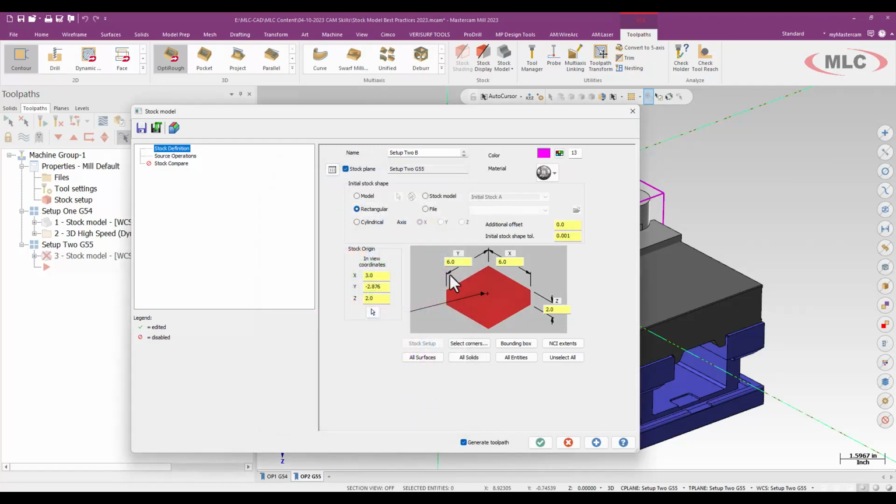And although I have the initial stock shape here initially defined, and that just carries over from the last one, I can also, as I get further down the road, want to apply just the previous model. So the initial stock shape for this model would just be whatever the last stock model sort of ended as. And that way you can sort of link and string all your stock models together. So if you go back and update an earlier toolpath, it does filter down to all the remaining models.